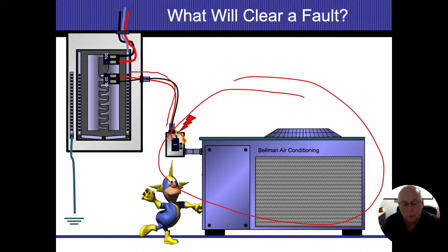If I had a ground wire coming back through it, then that ground wire would bring electricity back to the case, get it to my neutral bus or neutral bond on here. The bond would get it onto the neutral bus bar. That would allow free flow of electricity, and that's going to allow everything to clear the fault and allow the breaker to trip. And that's our big audacious goal again. We want that power to turn off as fast as possible.